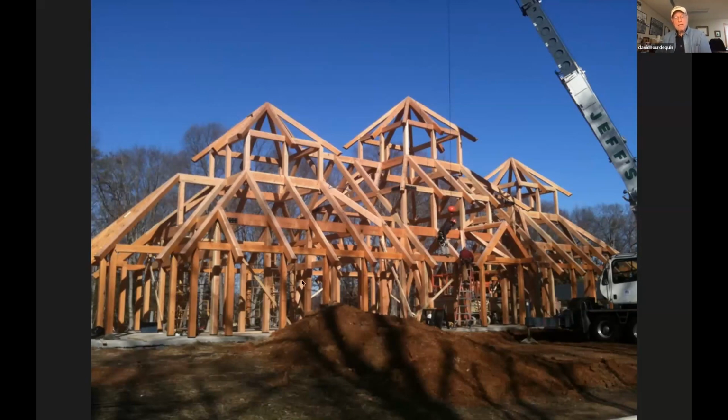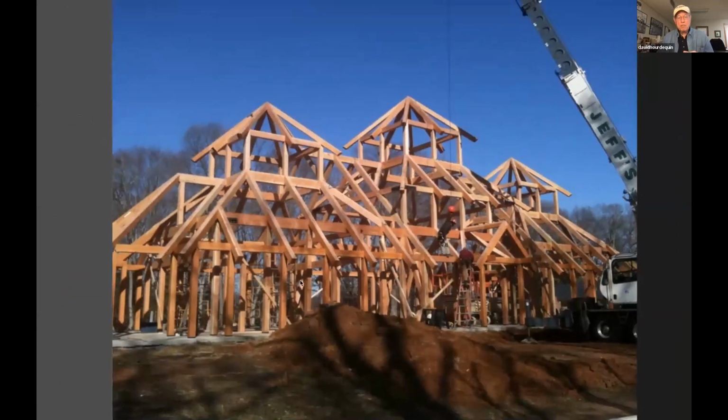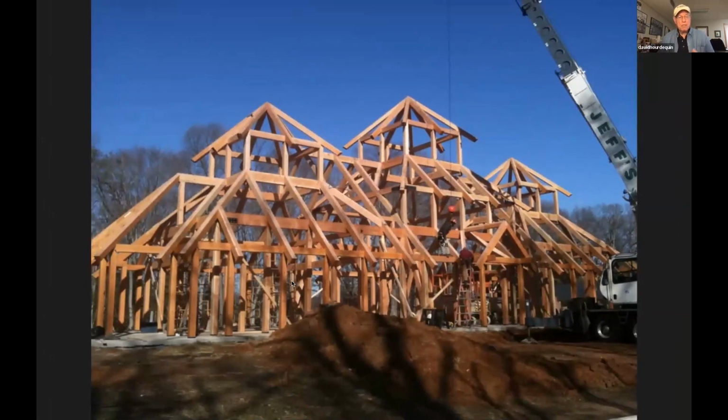In a timber frame structure, the walls normally pass outside of the timber frame. The reason is that the posts that support the structure will tend to shrink over time and move, and you don't want joints opening up inside the building. So you allow the wood frame wall to pass outside, and where the wall is at a post, you connect it to the post to transfer the shear wall loads into the post to go down to the post connector. If there's not a post convenient to do it, sometimes you have to use an embedded Simpson anchor or something like that. So that's how that is done.